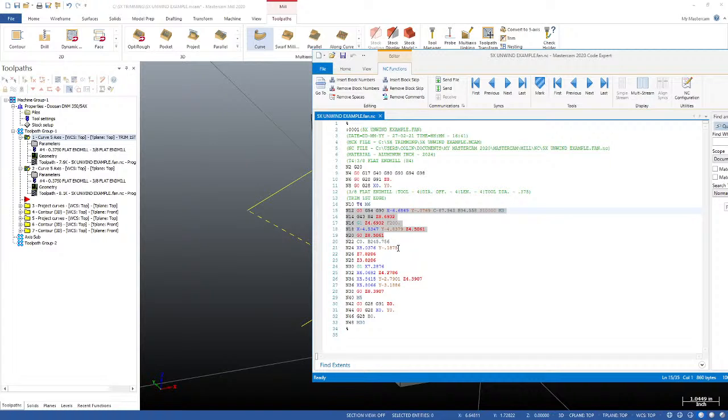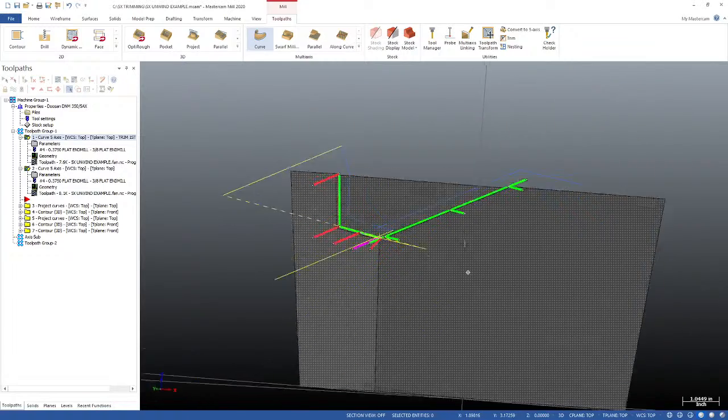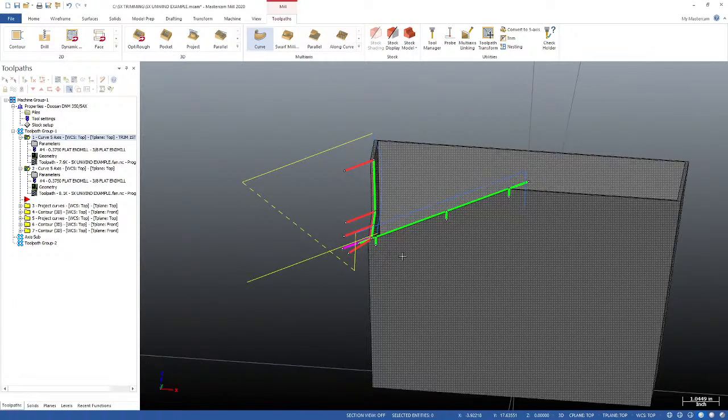But then you notice something that happens. I've entered and exited the cut, and then all you see is this rotation. So this rotates from my first cut here to my second cut, and then I've got some other approach move where the tool moves to the next position. So I have to be aware of getting my tool into and out of the cut. So basically from this cut, I have to safely be able to transition to my next cut. That is not going to happen if my tool ends down here.